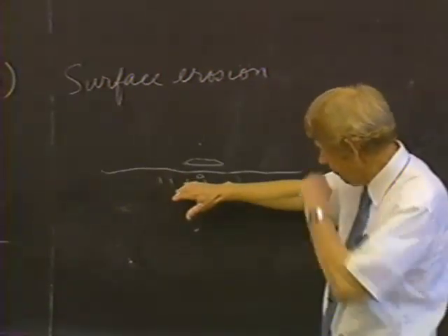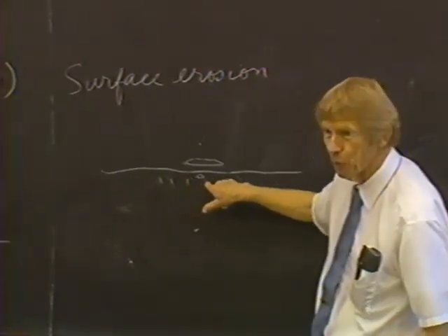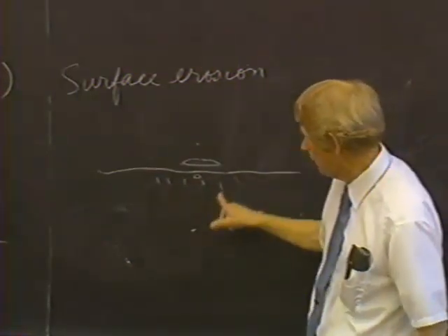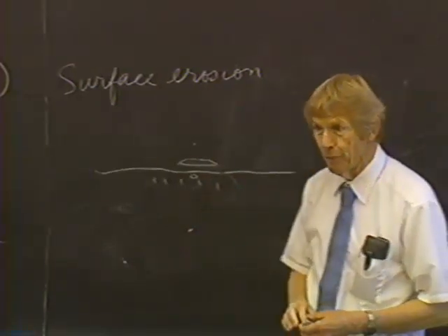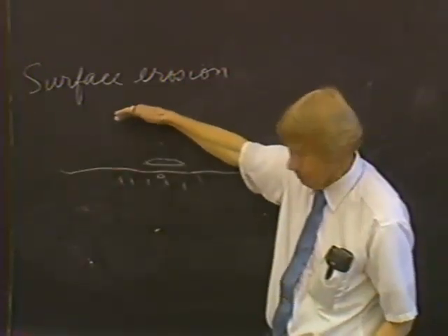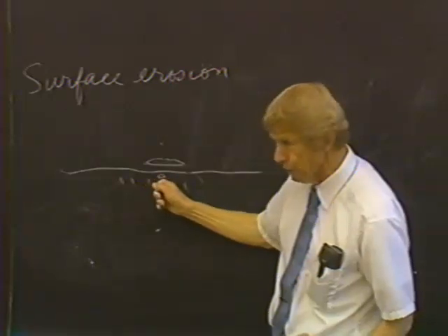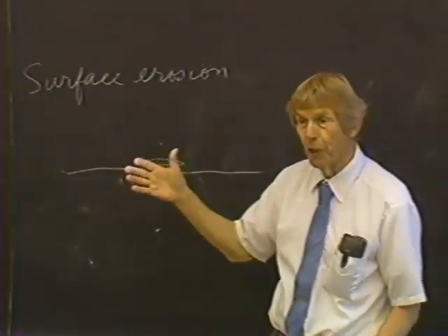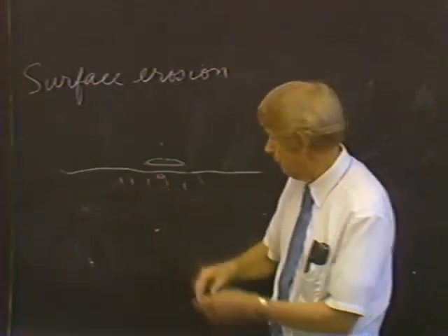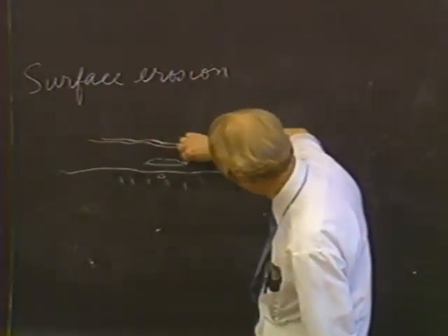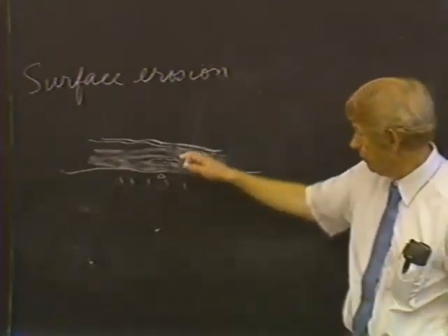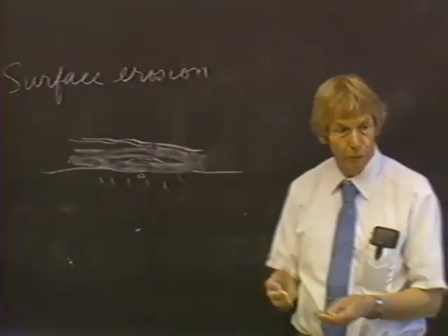I once put mud in a flume and put little dime store pearls next to the glass, and you could actually see them as the wave went by. You could see the pearl moving under the mud. If you increase the amplitude of the wave or steepness, what you'll find is that this grows and grows, and then pretty soon the deformation of the mud destroys the structure of the gel, and it fluidizes, and you get a layer of turbid water above it. It usually has quite a sharp interface, in fact. A turbid water above it, it just fluidizes it.